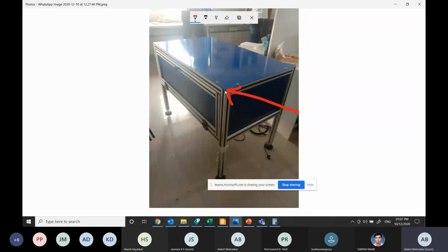If there is a sudden impact to the base, then the complete robotic structure will vibrate or deflect, and because of which the gripper will suffer from maximum deflection. How much deflection will be there in the gripper can be analyzed using the response spectrum analysis, which is also called the earthquake analysis, where the input in the form of acceleration has to be applied. That we have discussed in the morning.